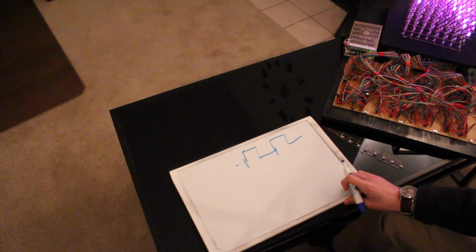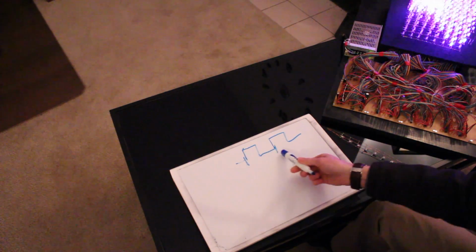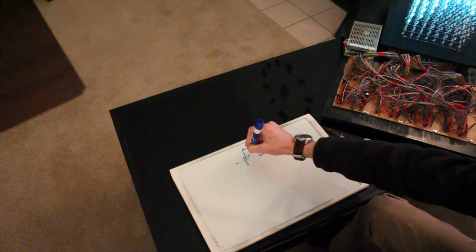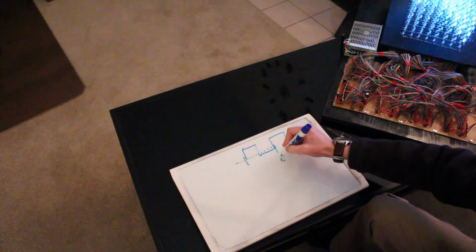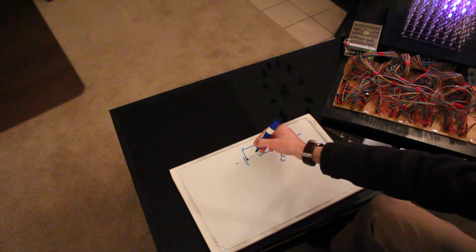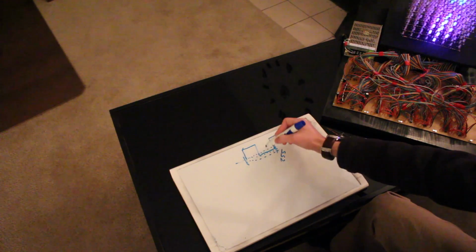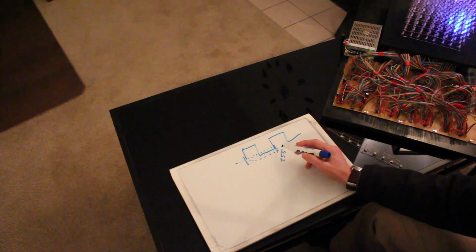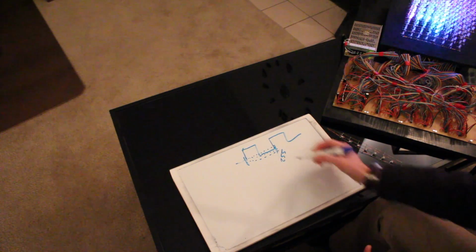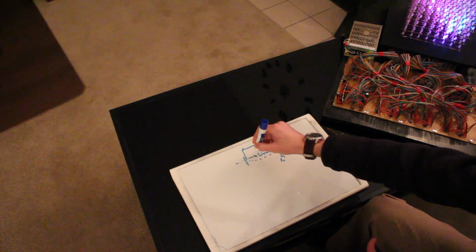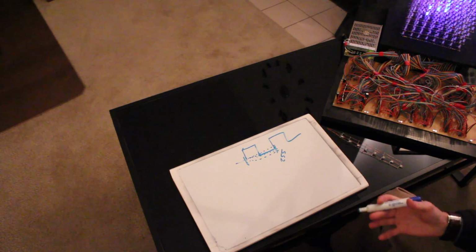What bit angle modulation does is, instead of having this fixed carrier, where each one of these ticks goes all the way to 255, basically this is a counter running in the background and it counts up all the way. And as soon as you hit, say, 127 with an 8-bit resolution, that would be 50%. As soon as the counter hits 127, boom, it turns the pin off. So that's like standard PWM. That's how it works.